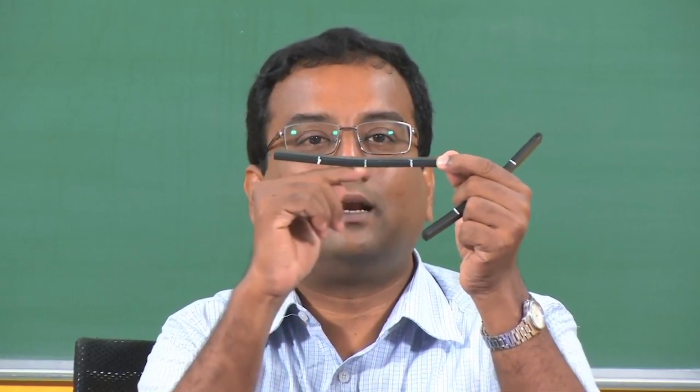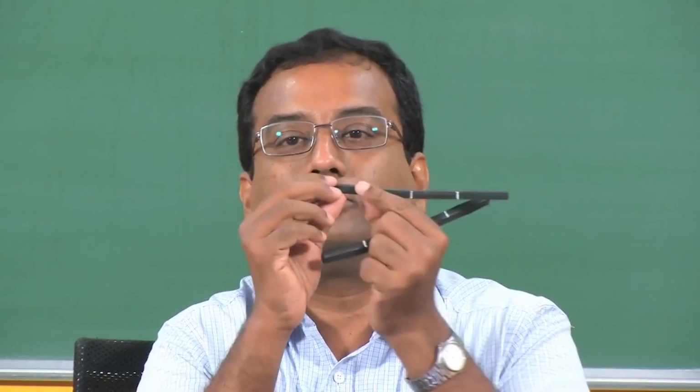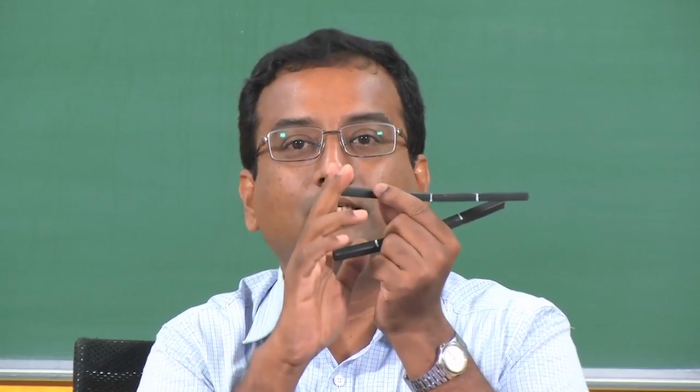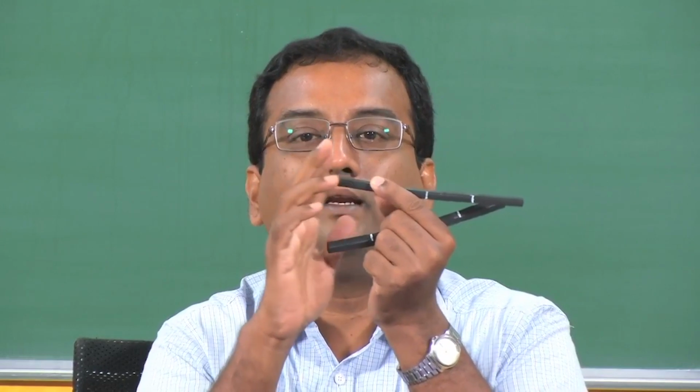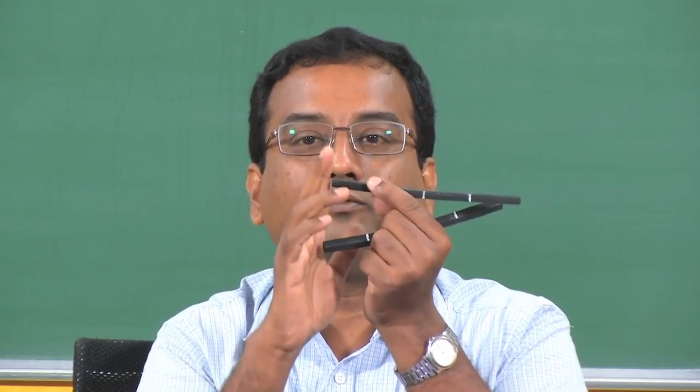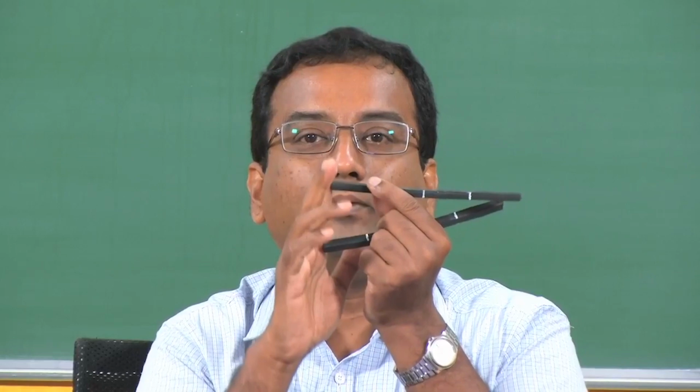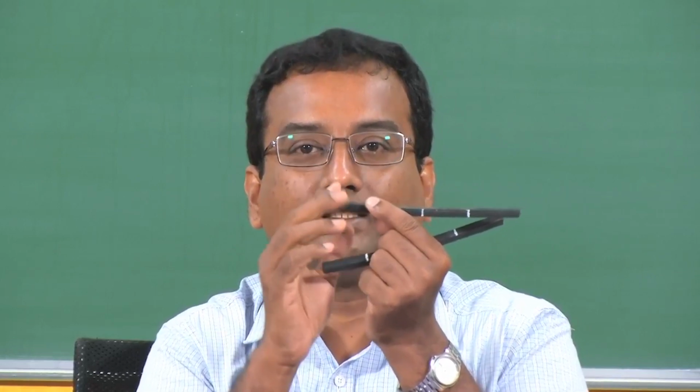Okay. The shear stress developed at this interface has to be countered by a complementary shear stress, which we saw from moment equilibrium has to be the same as the shear stress developed here. For moment equilibrium, there should be a complementary shear stress developed at this face. Okay. So, that is what we are going to do. We are going to do this calculation systematically now.